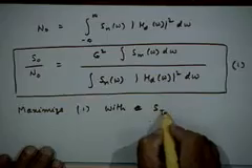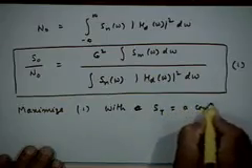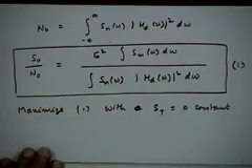But obviously there is a limit to the amount of signal power that you can transmit for various practical reasons, so there is a constraint with which you have to maximize this, right. So basically you want to depend only on filtering to do your optimization, to increase your output SNR, not the brute force solution of increasing the transmit power, right. So maximize equation 1 with the constraint that S_t should be equal to some fixed constant. Okay.